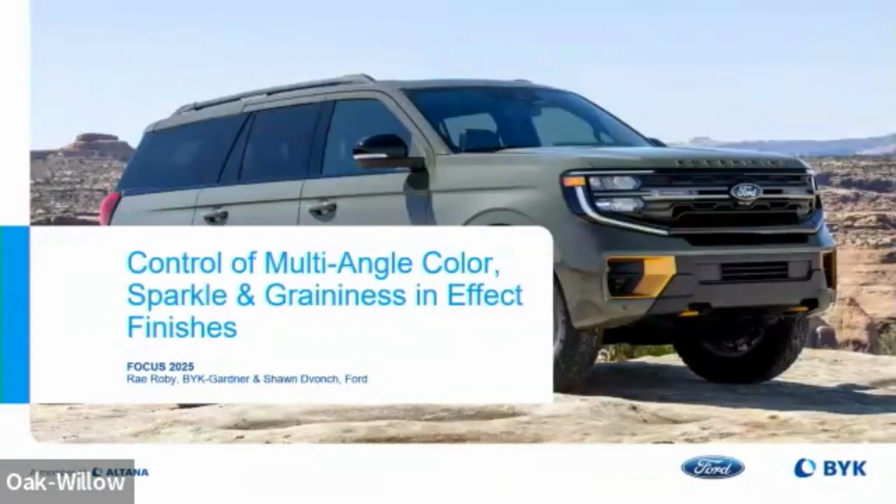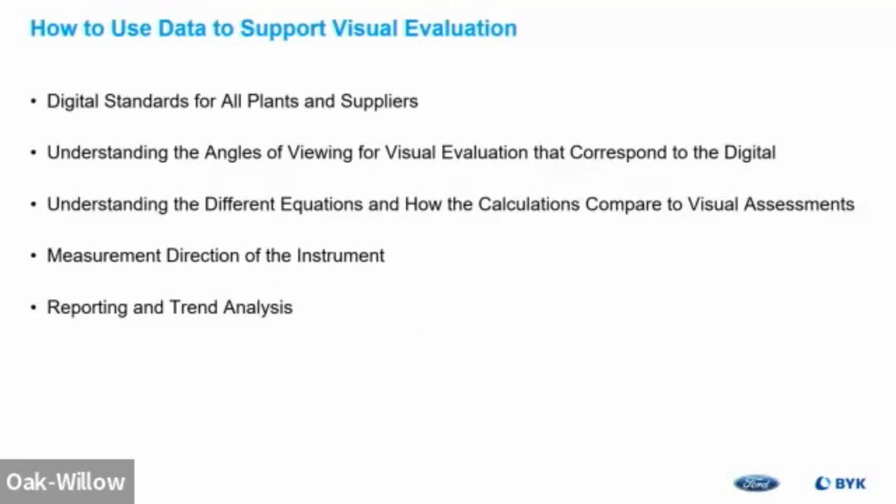Hopefully it works. So today we're gonna talk about control of multi-angle color, what's important, what you need to pay attention to when you're working on these kinds of things. So the first thing with this, you need to have digital standards for all your parts or your plants and your part suppliers. You really need to understand the difference in what you're looking at on the vehicle and what angles are actually being measured.